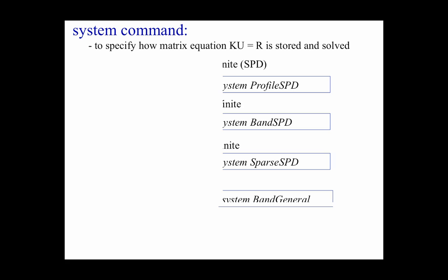Okay? These other solvers are nice for checking at the start, because some of these sparse solvers will actually give you a solution when your model is negative definite, or even round off when you've got some rigid modes that you haven't taken care of, where your fixity condition isn't right. Some of these solvers will actually work. They'll give you an answer because of what's going on in the hardware with the numerical computations, whereas these other solvers will typically fail. But large models always use a sparse solver.